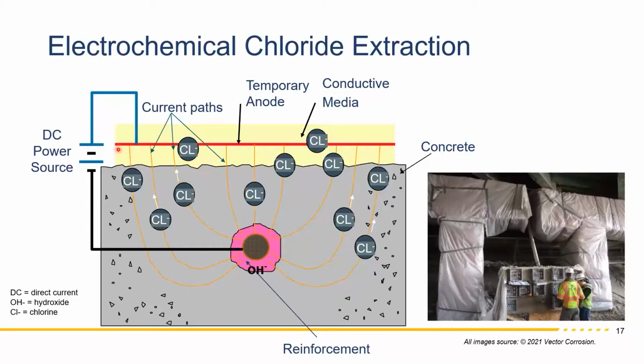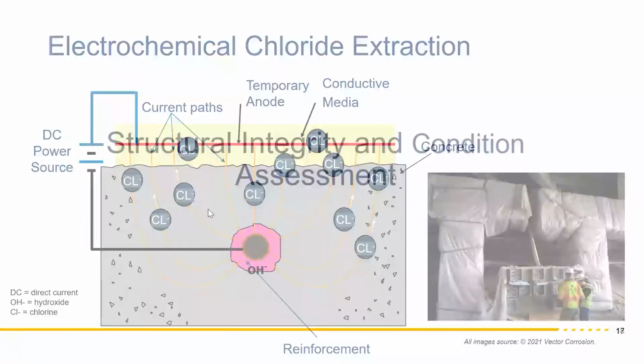You have to have rectifiers to make sure that this current is constant, because there's temperature dependency and moisture dependency. So it's an involved process, cathodic protection, but it's well worth taking a look at, especially in marine environments and splash zones and so forth.